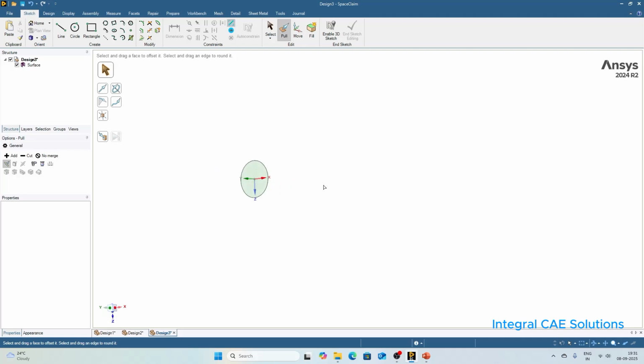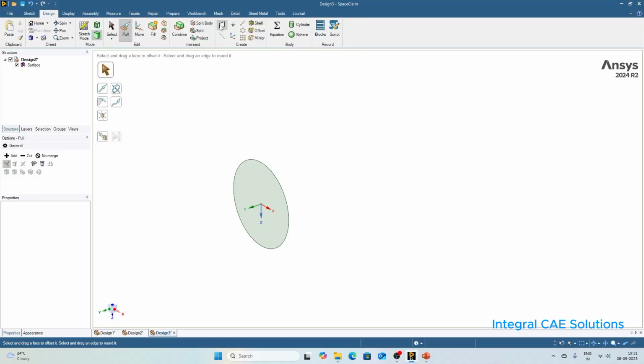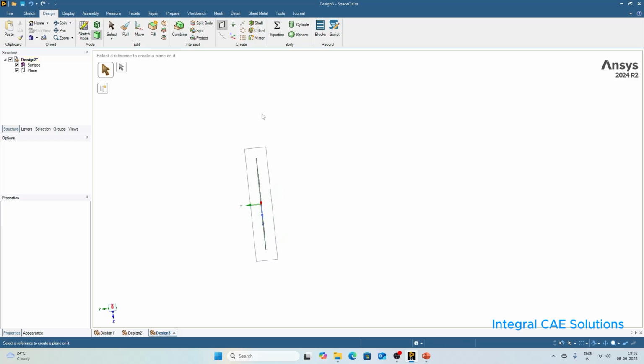Now in order to create that 90-degree elbow, we will need a sweep path. So this will be swept along this random path. But in this case, we will have to create a sketch for the path. So let's create a plane. Select the plane option from here. And if you want a plane on YZ, then you can select the X-axis arrow. You can see that the plane will be displayed. Once you click on the X arrow, the plane will be created perpendicular to the cross section.